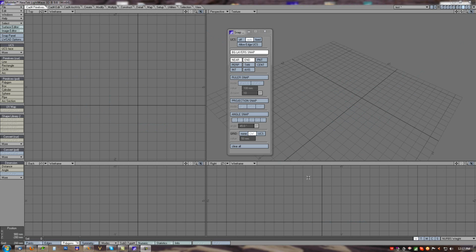There are also some updates in the snap panel. The axis snap was updated in this version. Now if we are using angle snap, or if we are constraining the tool by holding the Ctrl key on the keyboard, it will create a nice intersection snap between the axis snap and the constrained line from angle snap or holding the Ctrl key. This didn't work in the previous version very well.